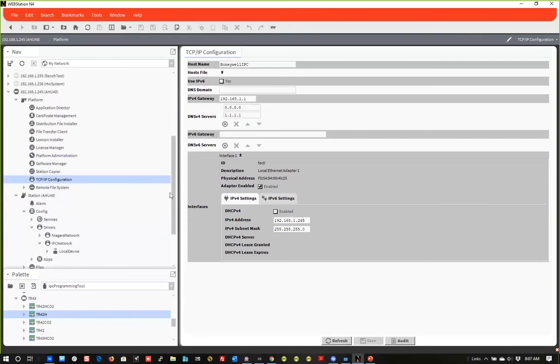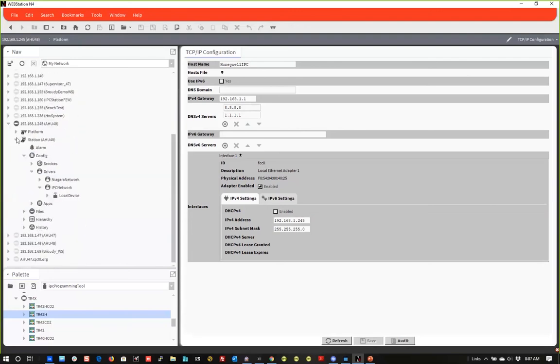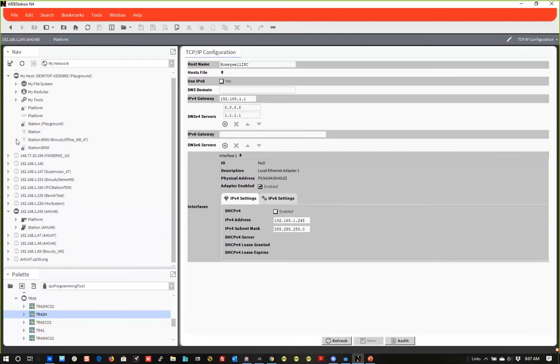Any other questions? I could see down the road going into more, and you'll learn it in class too. One of the questions that'll come up is, I've got 100 VAVs, I need to do this, and I have to commission each controller like a Jace individually. That's going to take a long time. Well, one of the big things with Niagara is the provisioning that you can utilize. You can set up a batch for configuring and deploying each of the devices. So there are tools in place to make that easier.